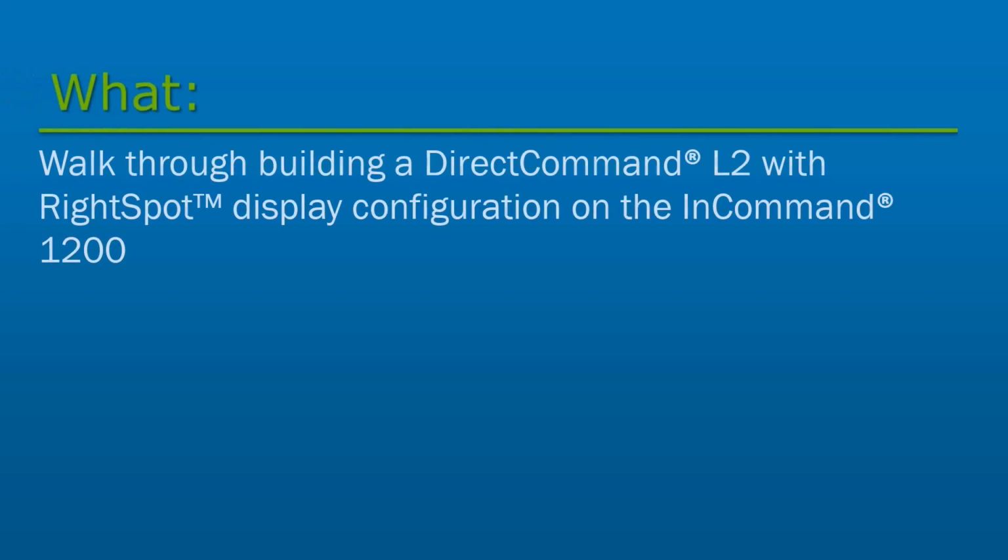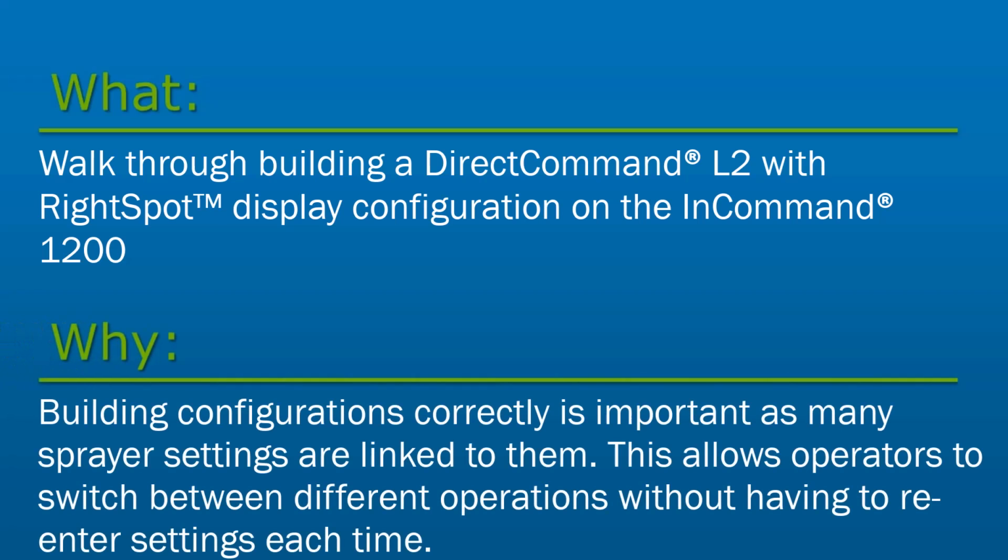In this video, we will walk through building a DirectCommand L2 with RightSpot display configuration on the InCommand 1200. Building configurations correctly is important as many sprayer settings are linked to them. This allows operators to switch between different operations without having to re-enter settings each time.